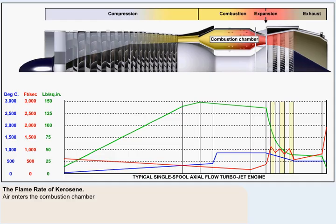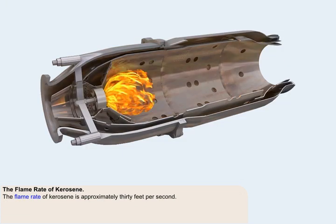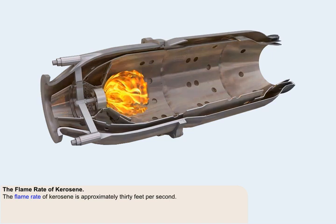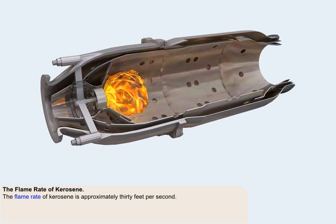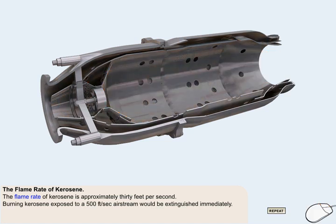You'll see from this graph that the air enters the combustion chamber at a slightly slower rate than which it enters the intake of the engine. Speeds of around 500 feet per second are not unusual. The flame rate of kerosene, that is, the speed at which the leading edge of a flame would travel through kerosene vapour, is approximately 30 feet per second. If burning kerosene was exposed to an airstream which was travelling at 500 feet per second, it would be extinguished immediately.